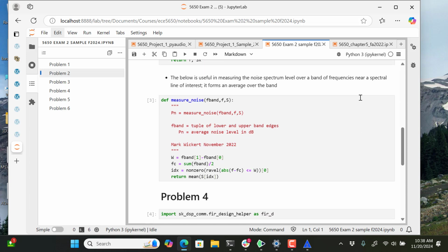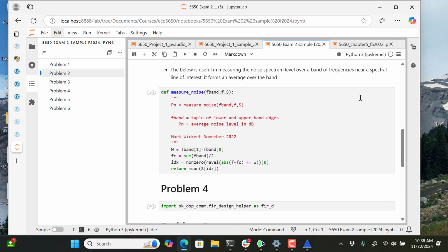You'll see the noise floor from the quantization noise in the simulation, and then you'll also see the spike. In order to get the noise power measured, I'm giving you this function. You'll have a spike right here, and then you can set two bands with this function that you want to measure noise power adjacent to the spike. So I set one below and one above, and then I get those estimates out of this function, which will be this mean value over that interval, and then I add them together and divide by 2. So I just get a measure of the noise floor, and that goes into the formulas. There may be some questions on it, but it's pretty straightforward beyond that.